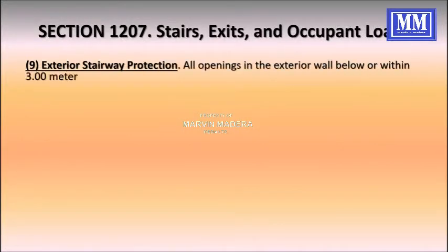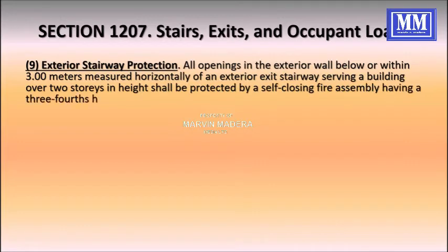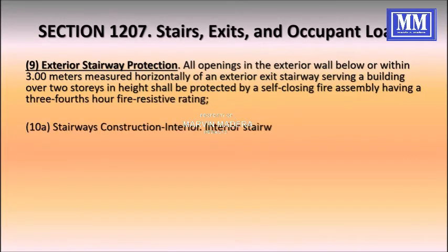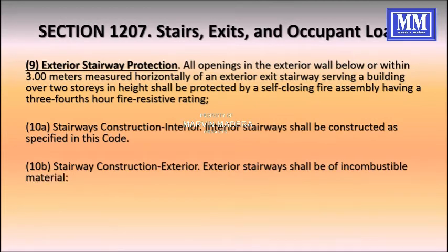Exterior stairway protection. All openings in the exterior wall below or within 3 meters, measured horizontally, of an exterior exit stairway serving a building over 2 stories in height shall be protected by a self-closing fire assembly having a 3/4 hour fire resistive rating. Stairway construction, interior.